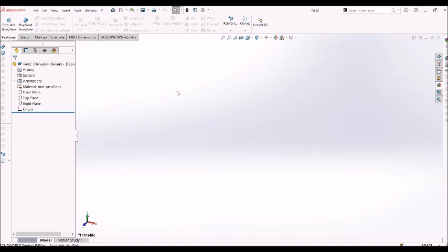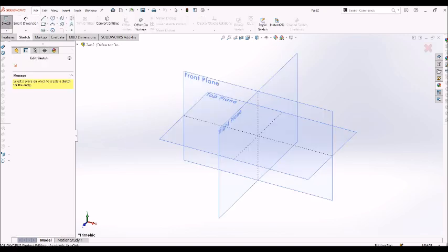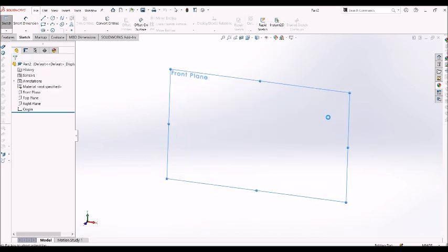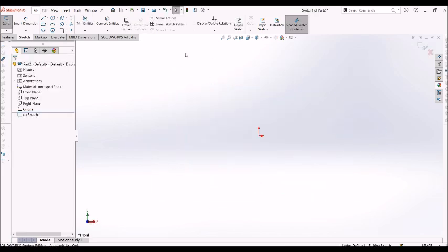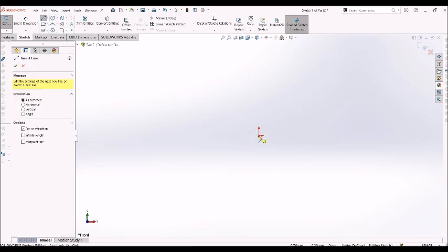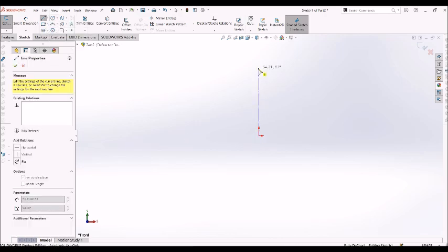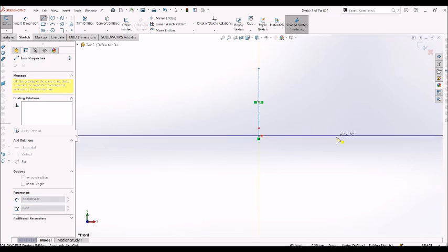So first thing we need to do is click sketch, like usual, sketch button, and then we need to choose our plane, and we're going to make this on the front plane. So when we have this, first thing I like to do, center line, and our little shape across the origin. Straight up, straight out to the side. Remember to look for the little yellow box.